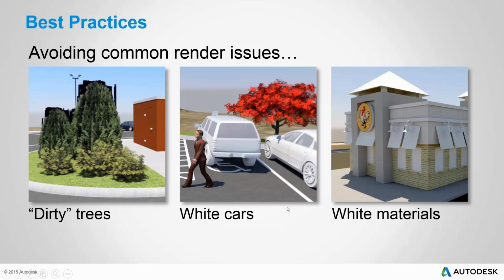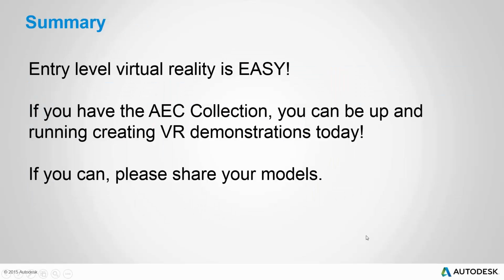So we've addressed some best practices here, ways to get around some of the common things that I've seen in the last couple months doing this. So in summary, we've learned that entry-level virtual reality is actually quite easy. We can do it in just a couple minutes. If I have an InfraWorks model, I can export that right through Navisworks and create a cloud rendering that creates a virtual, very immersive environment.